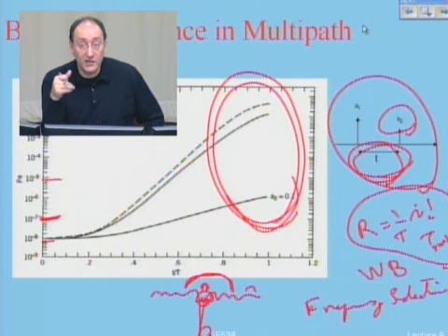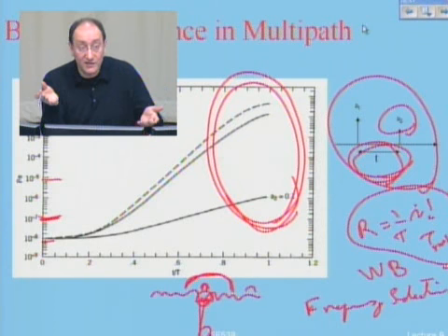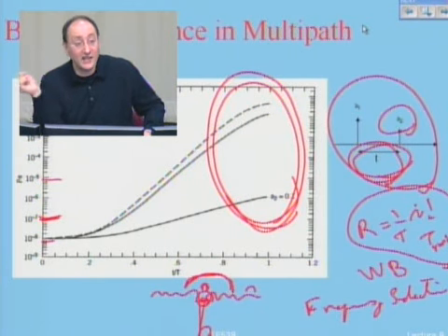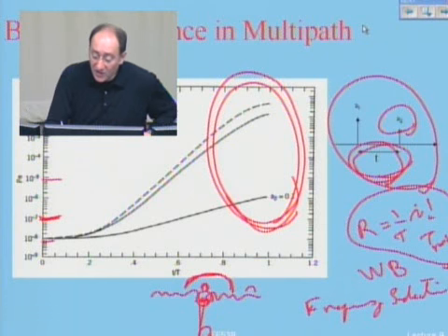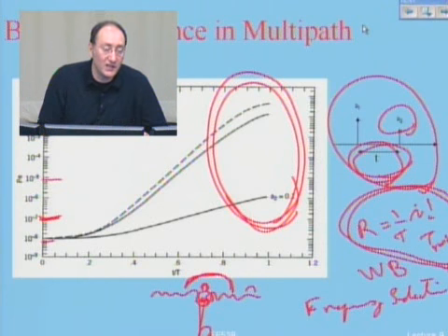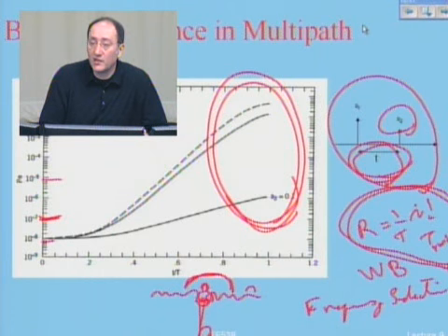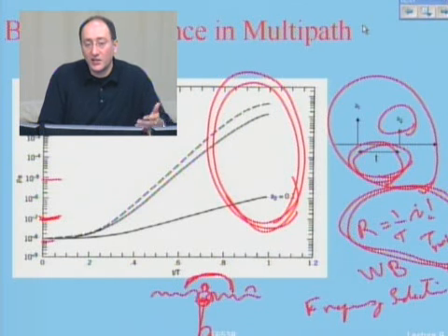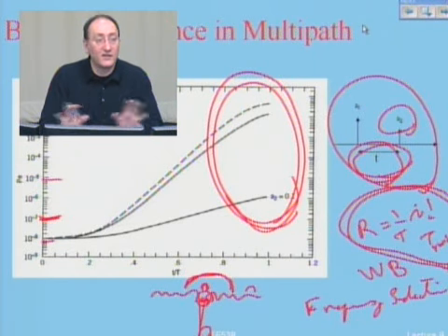And sometimes it's very confusing because when I look at the channel, it's always wideband. Always it is frequency selective. But no, it means for that particular modem, I have this condition or I don't have this condition. So I can call it narrowband and wideband equivalently. Narrowband communication in information theory means communication over a flat fading channel. Wideband communication in information theory is translated to communication over frequency selective fading channels. These are just different terminologies.